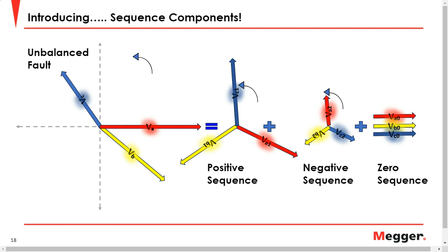I see in the Q&A a comment that's very valid that says that the delta filters out triple harmonics. And that refers to my previous question. Since they behave like zero sequence components, it stands to reason that they're also filtered by the delta, which means that they remain circulating inside of the delta, which doesn't mean that they are not present on the other side.